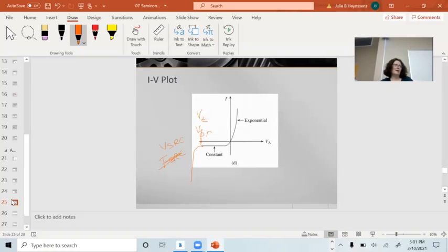This is the start of how people build those linear voltage regulators. They use a Zener diode, which isn't perfect. It doesn't have great output impedance. And then they put a big amplifier around it, and an amplifier on the end. They put some stabilizing circuitry in there, and then you have a good linear regulator. So that region does exist, and it doesn't involve breaking the diodes. There's no smoke involved. It's non-catastrophic as long as you don't get the voltage too high.